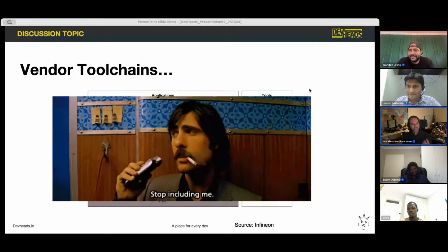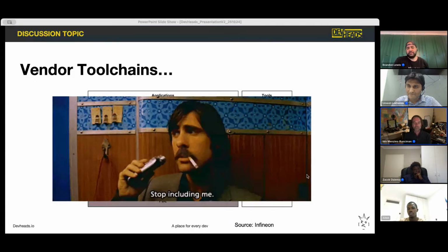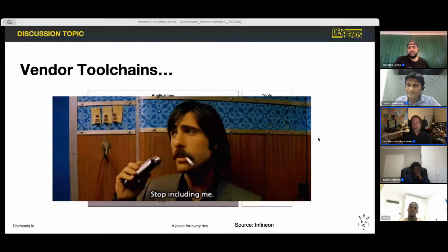Well, I'd say instead of a horror story, you can say this is why I love the Yocto toolchain. Because I know that if I'm using a toolchain built by my Yocto project, for starters, if I'm compiling something and I've compiled it against that development kit, it's going to run on my board. And then the other thing is, because I kind of built it myself, I know what went into it because I put it there. Yeah.